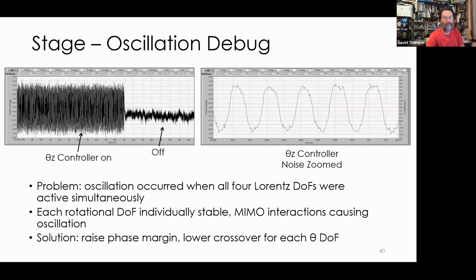The downside is you're not fully encompassing the MIMO aspect of the problem, but we managed to hack our way through this way. Whereas if you just fed all this into a MIMO LQG design problem and you get a controller and you run it, it's unstable. You really have no idea what to do next. This lets us work our way up through getting things to operate.